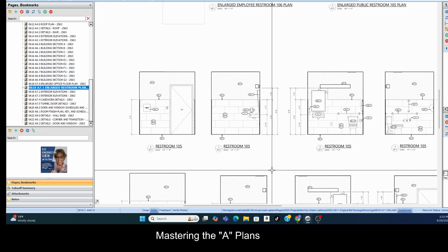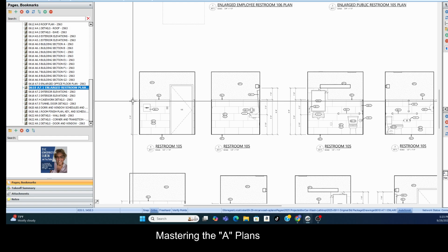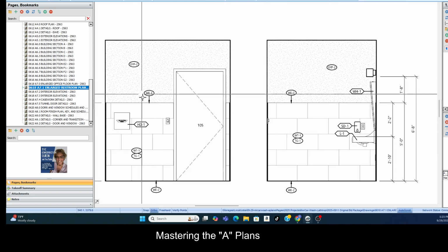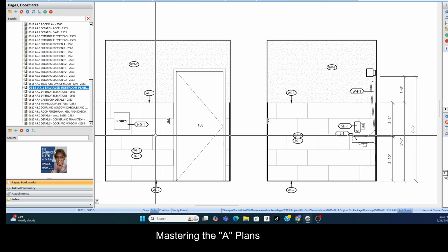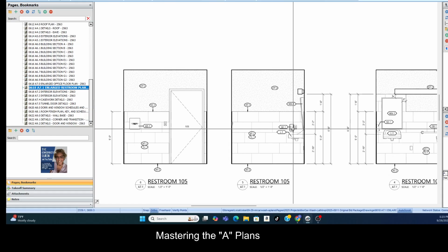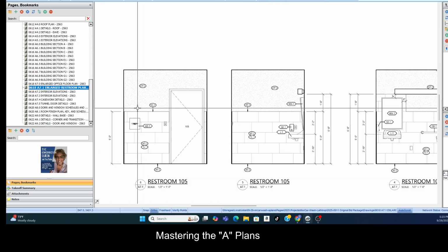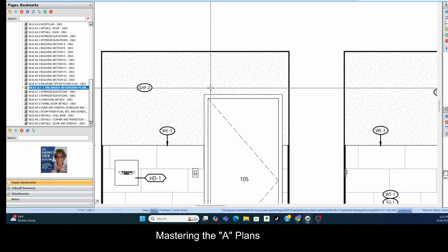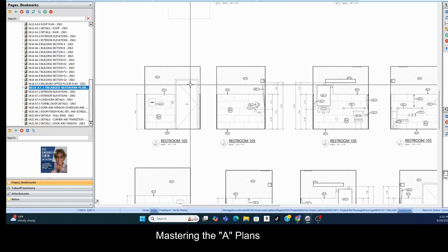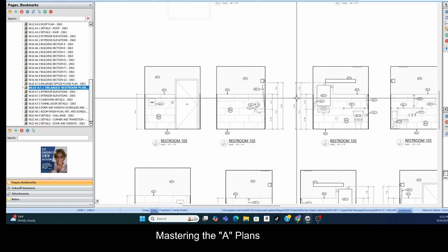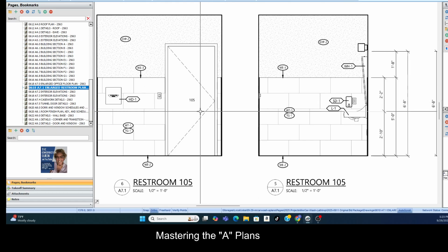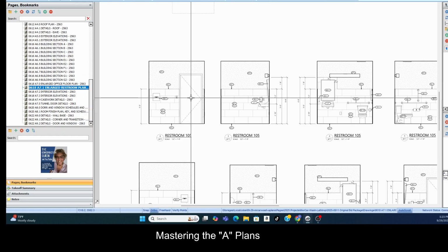All right, so what do we have here? Interior elevations for the bathroom. And so I know now that's some kind of wall tile, okay? I know how much I have because I can measure this very easily. And if I'm the painter, I can measure that too. And I'm probably painting the doors as well, but the door schedule will tell me what the finish is on particular doors, because each of the doors has a number.